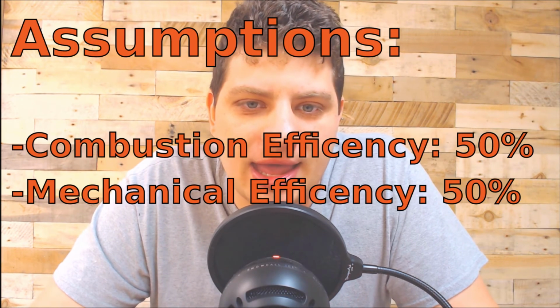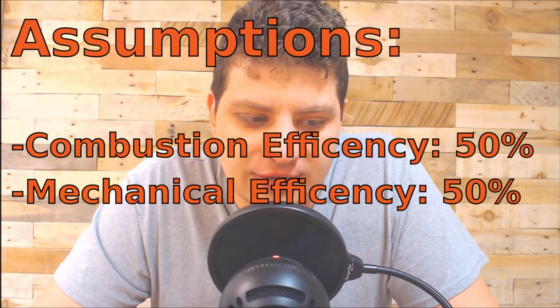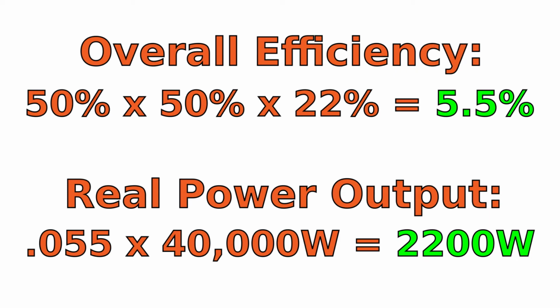Now let's try to predict how much power we'll get out of this engine using our efficiencies. If we assume a combustion efficiency of 50% and a mechanical efficiency of 50%, and we know our thermodynamic efficiency is 22%, you get a potential power output of 2.2 kilowatts. That's about 3 horsepower, which would be a decent lawnmower. Now that is still a lot of energy, and frankly, I don't think that this engine will even do this well. But the fact that it could do that well is exciting to me.